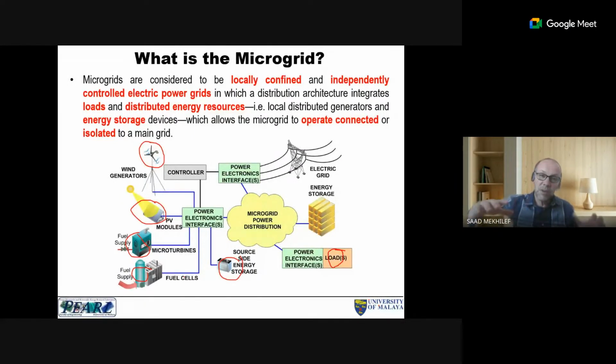Sometimes you have the volume, the Q. The micro hydro depends on two factors, the head, which is the height, and also the Q, the amount of water. So it depends on the resources, but it can range from a few kilowatts to megawatts.